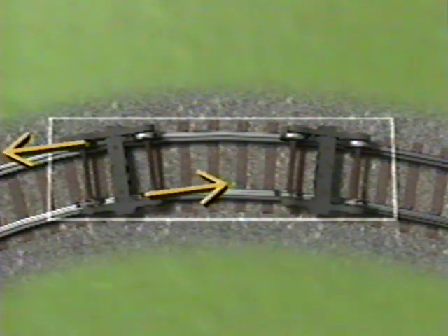Another factor that can prevent a truck from turning properly in a curve is poor steering. Steering refers to the forces that guide wheel sets and trucks through the curve. They are generated along the rails in the longitudinal direction. The picture shows steering or longitudinal forces in the proper direction to rotate the truck and align it in the curve. However, longitudinal forces can be generated in the opposite direction, such that they resist truck turning. This is referred to as poor steering.